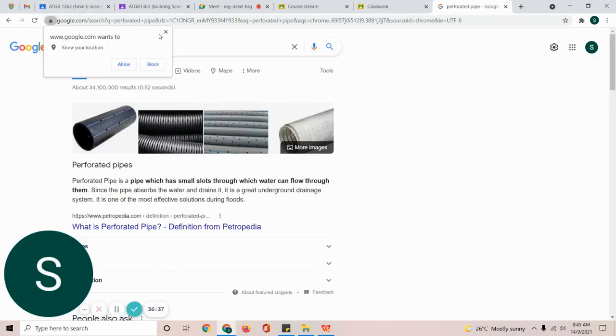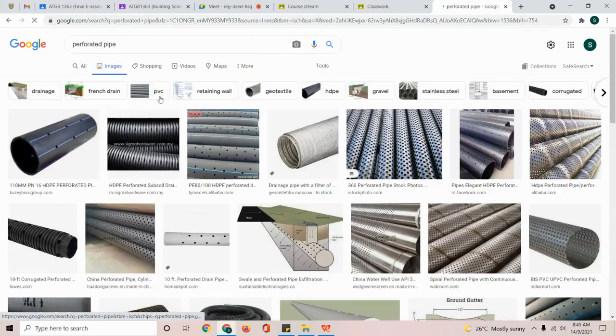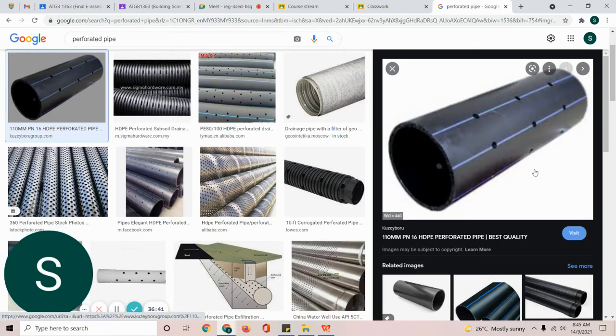So it actually just looks like this. It's an HDPE pipe. Usually we do not buy pipe with holes. These small holes are what we drill out by ourselves on site. We just take a drill and drill into the HDPE pipe.